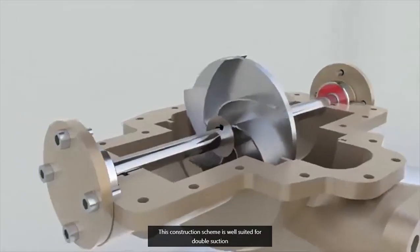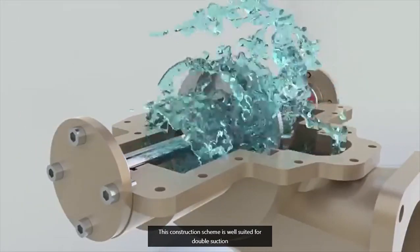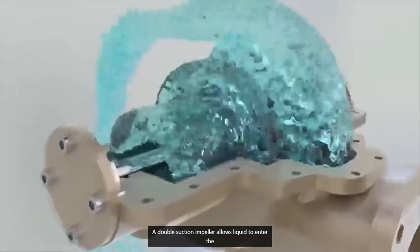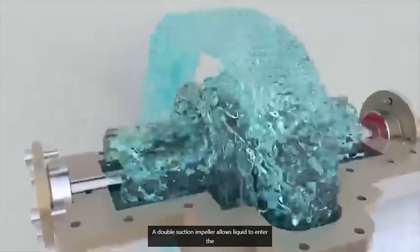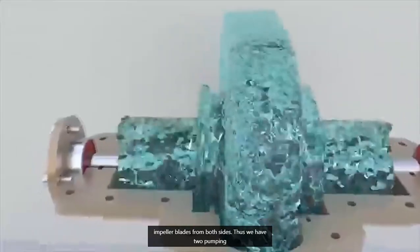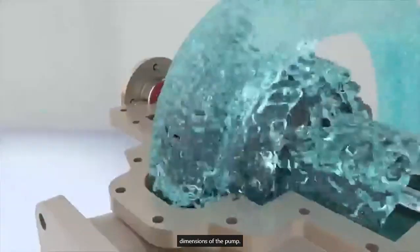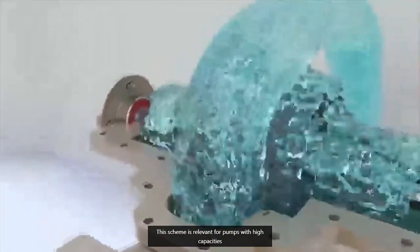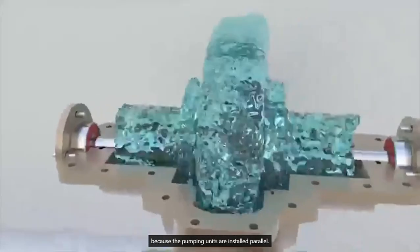This construction scheme is well suited for double suction impellers where the vanes are placed on both sides. A double suction impeller allows liquid to enter the impeller blades from both sides. Thus, we have two pumping units without significantly increasing the weight and dimensions of the pump. This scheme is relevant for pumps with high capacities because the pumping units are installed parallel.